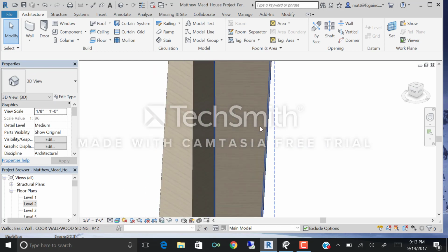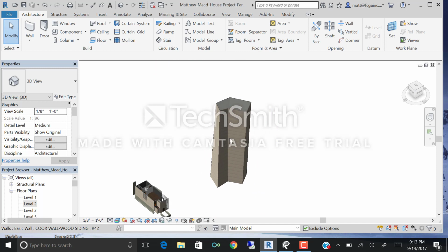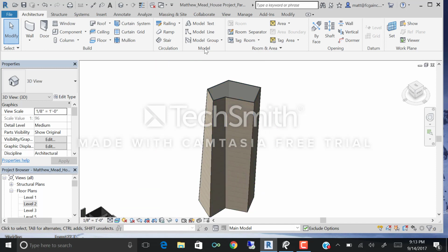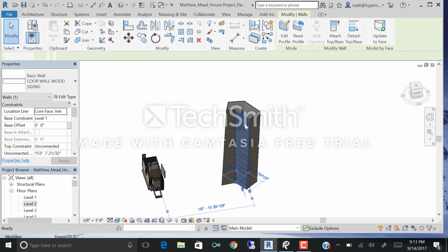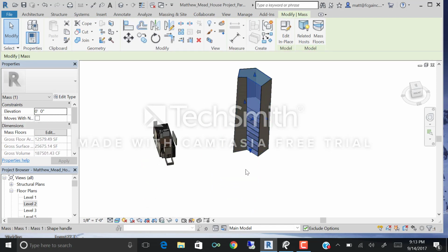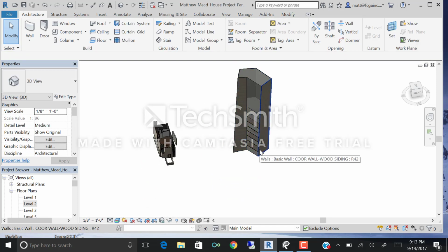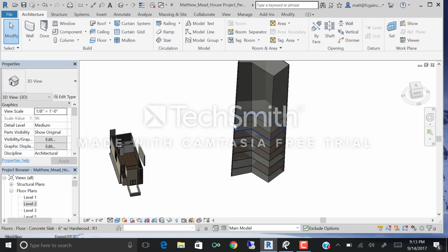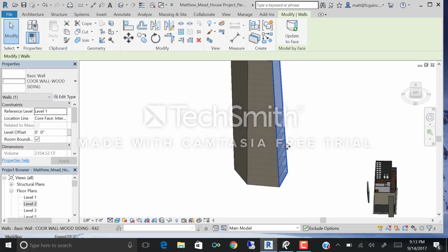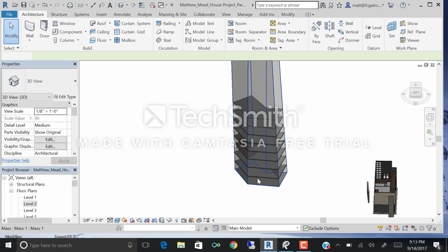Okay, just like you would add these exterior walls, you can also do the same thing for a curtain wall should you want to do all glass. Okay, we'll actually end up talking about that a little bit later on in the semester. Okay, but that gives you an idea about how the flooring by massing, how the wall by massing option works. Okay, if you wanted to add a curtain wall, I'll just quickly talk about that. Okay, let's get rid of these walls.